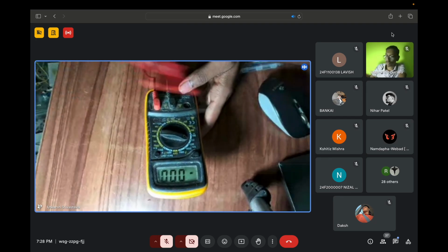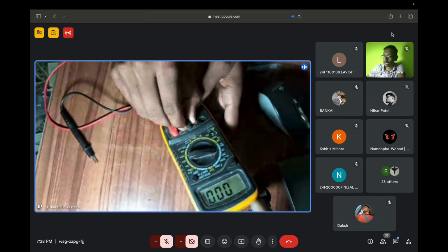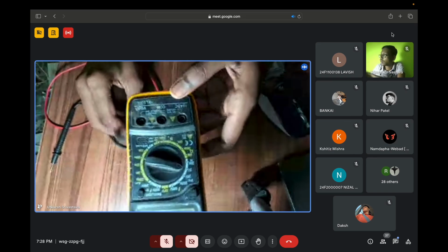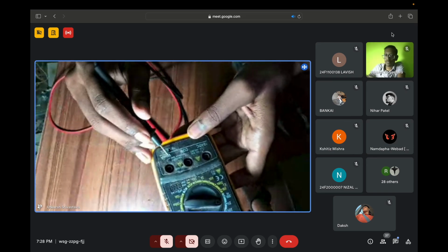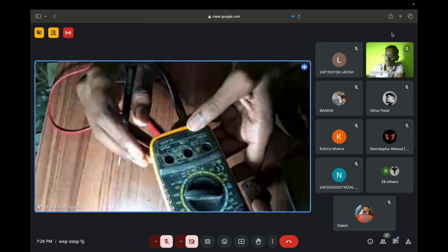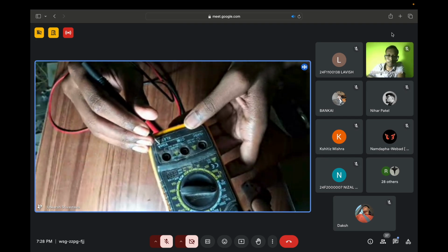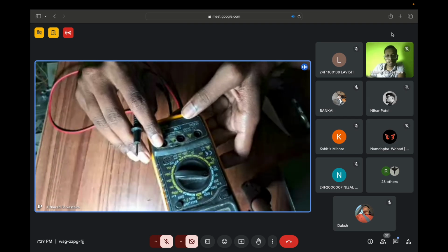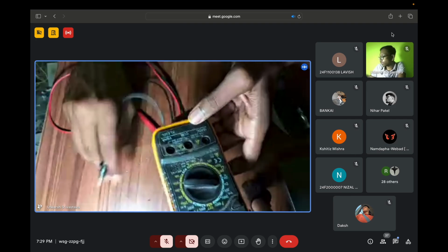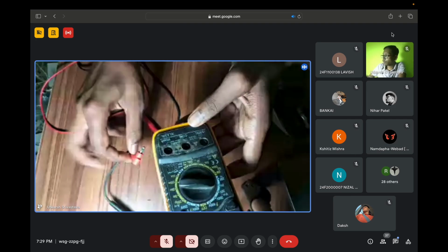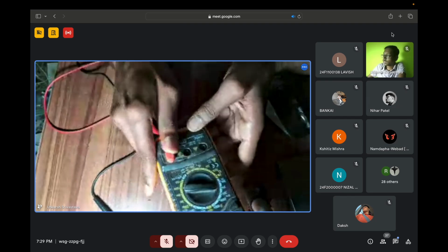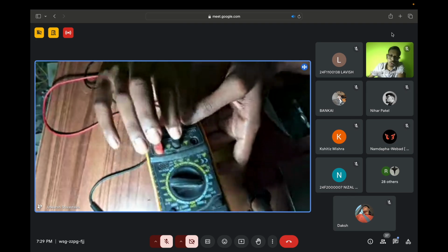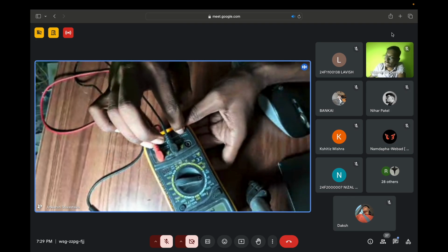And these are the probes. So in the multimeter, basically, 3 points are present over here. See, here it is showing V ohm and milliampere. That means if you are measuring the voltage and the resistance and the current which is under 10 milliamperes, you can connect this red probe on this. Okay. And the second option is the common. So this black wire always goes on the common. And there's a 10 ampere DC.